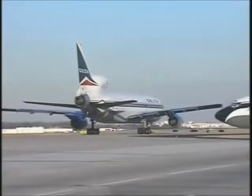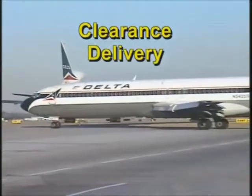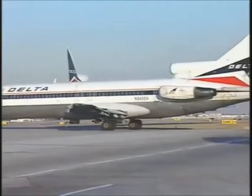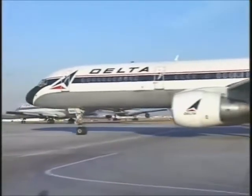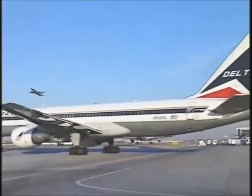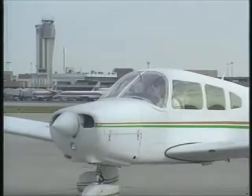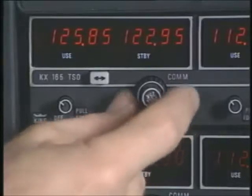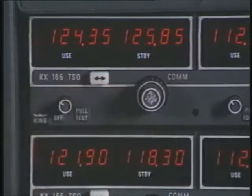Airports with a high volume of traffic may have a position called clearance delivery. It's primarily an IFR service, but can be used by VFR pilots to help improve the coordination of departing traffic. The controller provides you with a heading, altitude, transponder code, and departure control frequency to use after takeoff. If you want to use clearance delivery, contact the controller after listening to ATIS and before calling ground control. Inform the controller of your aircraft type, direction of flight, and that you have listened to the ATIS information.